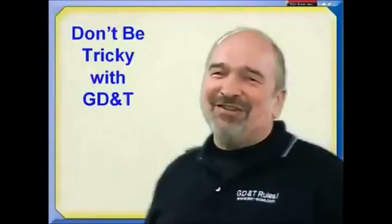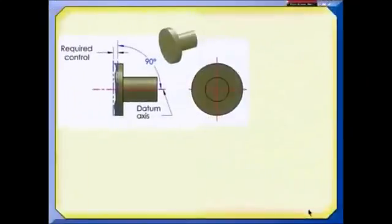This month's tip is, don't be tricky with GD&T. Let's say that the primary datum feature on this part is going to be this smaller diameter, which will establish an axis. The secondary datum feature is going to be this face, and I want to control its relationship back to the axis. It's a 90-degree relationship, so I want to keep it perpendicular. According to the Y14.5 standard, there are several different controls that I could use in this case.